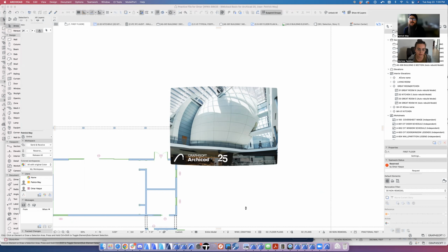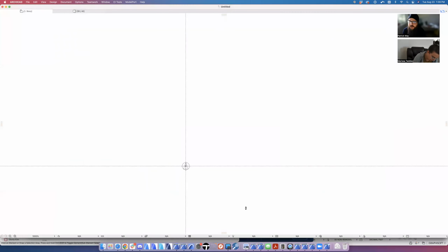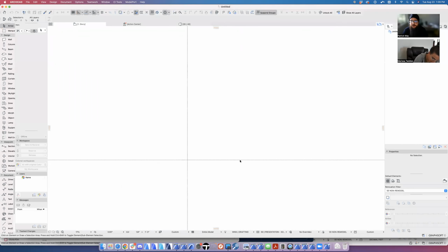Okay, so technically it could just be a drafted thing if you're really only going to see it in the interior elevation, and it's like a pegboard. So like the circles, probably at 1 inch on center or something, right? So probably best to create a fill. You could create a fill and apply that fill to a surface, and then that surface would show in 3D and in 2D. That way you're not drafting things over the top of a 3D model. So we'll go through that.